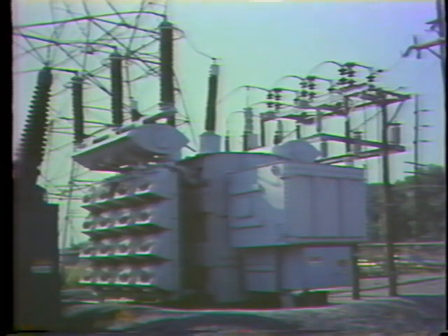Transformers are a very important part of your plant's electrical system. They can increase voltage for high voltage applications, or they can decrease voltage when lower voltages are needed. Let me give you a couple of examples. Suppose your plant's generators produce 15 kilovolts. Now, 15 kilovolts isn't the right voltage for very many applications. For example, the transmission lines leaving the plant typically operate at 200 to 500 kilovolts. So, a transformer is needed to increase voltage from the 15 kilovolts produced to whatever the transmission lines require.